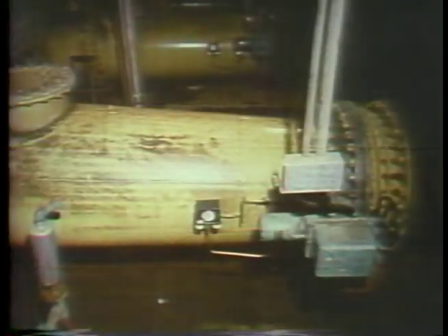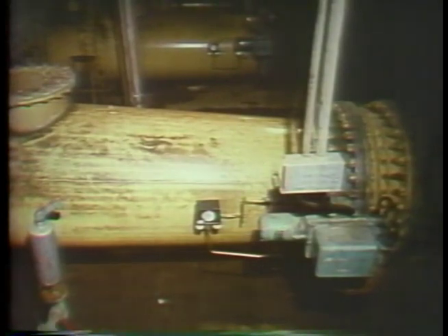The most accurate mass flow measurements are made by using a venturi. A venturi is a tapered restriction like we've been looking at. The narrowest part of the venturi is called the throat. Pressure readings are taken upstream of the venturi and at the throat. The venturi is designed to create a minimum of turbulence, which could affect the accuracy of a measurement. One example of a large venturi is the one found on some condenser circulating water systems. They're used to measure flow at the pump discharge.